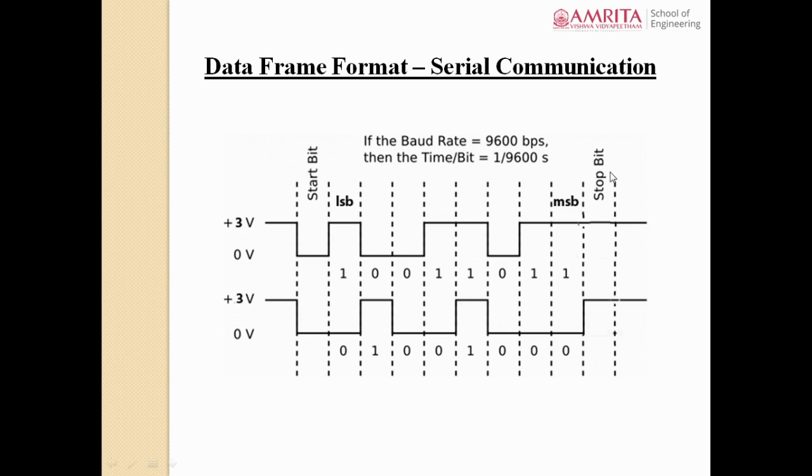What is the advantage of using a stop bit? By using the stop bit, you are taking the voltage level back from the previous state to the logic high state, because whenever there is no transmission or reception, the logic level will be logic 1. Similarly, after the completion of 8 data bits, the stop bit will take the TX or RX pin back to logic 1, right?